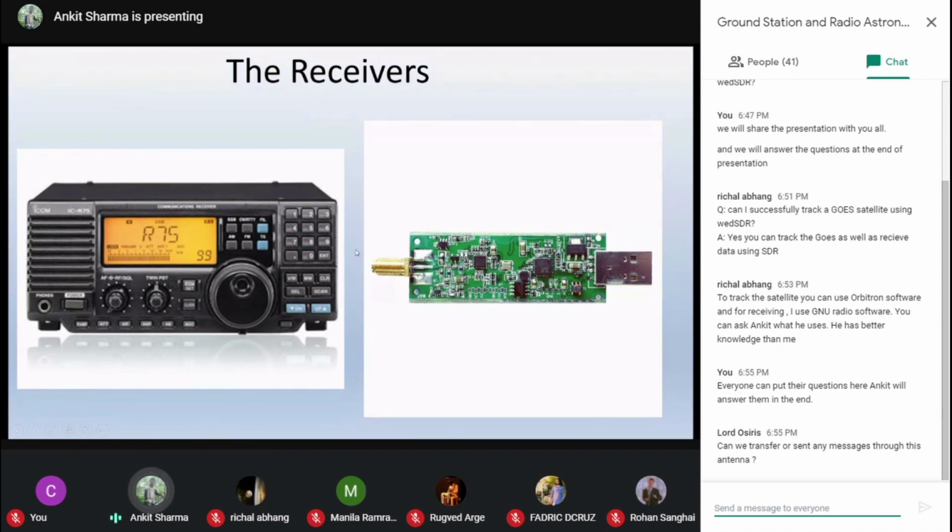Every coax cable has an attenuation ratio. Attenuation means they decrease the signal with the length, and so the coax cable should be short. No doubt, we also lose digital signals through the USB part, but it's very little, and the attenuation is so small that it's negligible. So definitely we have this practice where we keep the USB cable to the computer a bit longer, and the coax cable a bit shorter for these SDRs.